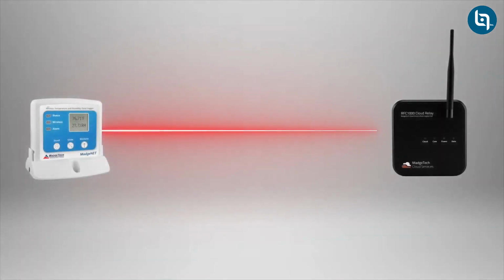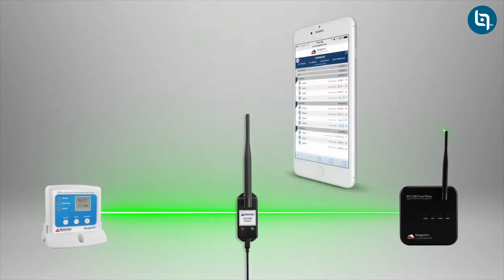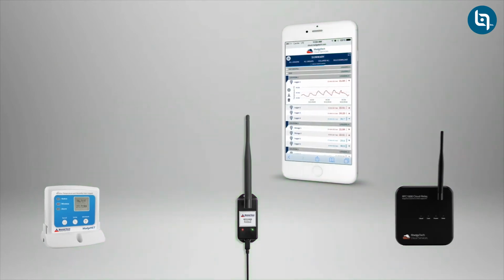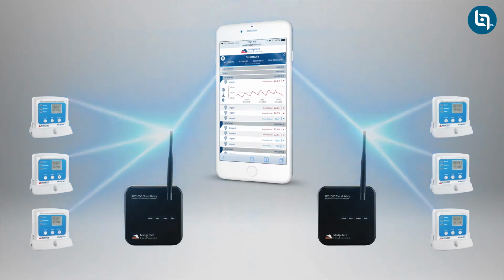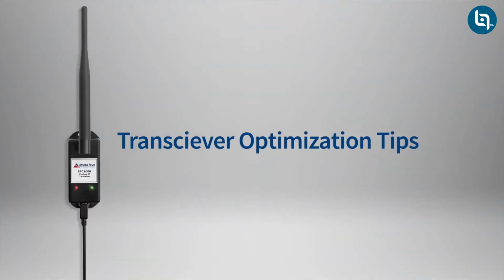In this step, we'll be deploying additional RFC 1000 transceivers to function as repeaters to bridge the gap between the poorly connected devices and the cloud relay. Alternatively, additional cloud relays can be used for remote areas or if using repeaters isn't feasible. Before we place our RFC 1000 wireless repeaters, let's go over a few optimization tips.